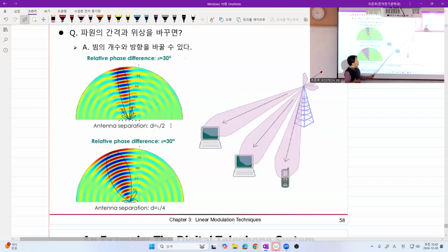But now, if you have array antenna that can steer, what can you do? You can just use the first channel. Now, first beam in the first channel carries Netflix. Second beam in the same channel carries YouTube channel signal, something like that. In this way, now you can save a lot of bandwidth. That is the idea of space division.